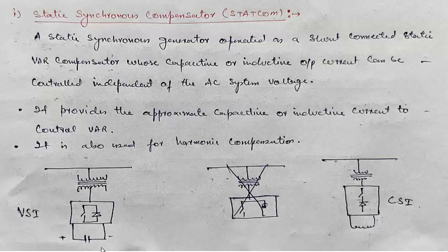Since this does the same thing, because it controls the reactive power and exchanges it without depending upon the system voltage, as was the case for the earlier controllers, which were capacitance based or inductance based, because they depend upon the system voltage.